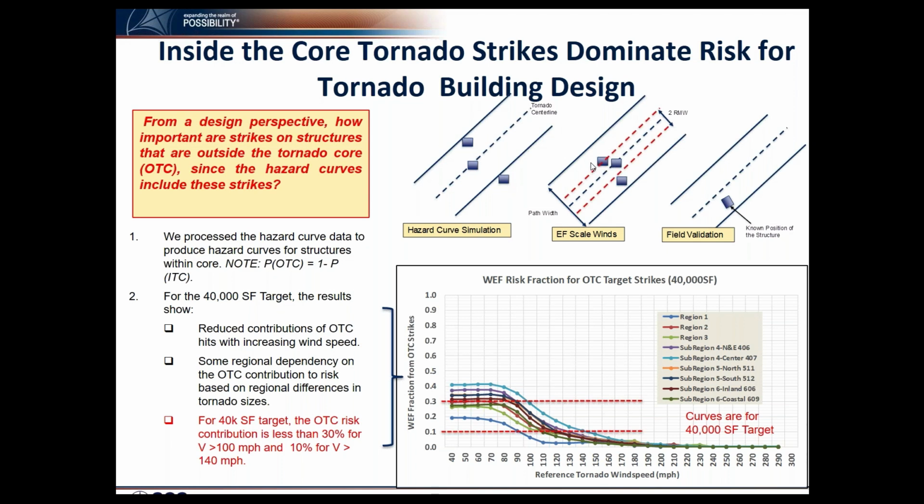Now, for design purposes, designers always consider whether the target is within the tornado core or not. How important is that when we interpret the tornado hazard curves? Here we did a study of the fraction of tornado out-of-core strikes with respect to inside-the-core strikes.